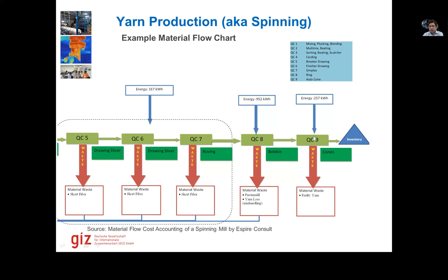In the auto coning process, there are a lot of very small pneumatic cylinders which are operated using the compressed air, and usually many of these are leaking, especially their connecting pipes. So normally they can be fixed only by pressing a little bit, but with the passage of time there's heat generated mechanically in the process, so these actually become brittle with time, and then we have to replace them. So this is how the process goes.